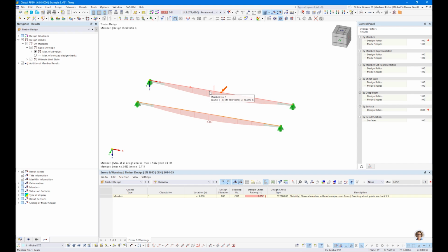It's not exactly factor 0.9, but in reality it should be factor 0.885, for example. And adding 2 times the beam height is also not perfectly correct. That's why we have a different approach. If you would use the German approach from the German annex, you would get a smaller buckling length, and then this should be nearly the same.